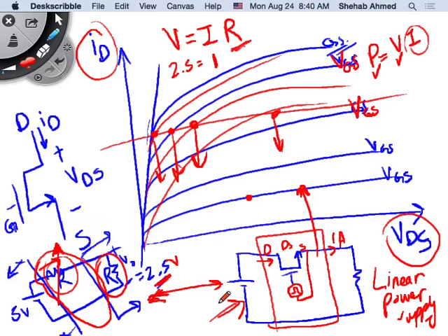Can I make something very small and so condensed, and make it inefficient? If I do that, then the heat will sort of eat up everything around it, right? So definitely the efficiency consideration matters if you have something put in a tight space versus something that has a big space to operate in. If you have a big area or big surface, the heat will dissipate, so you can live with a lower efficiency there.